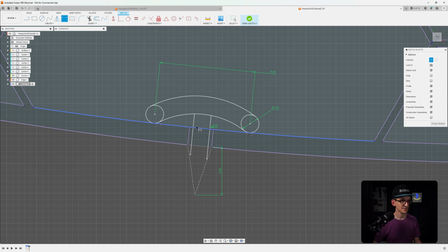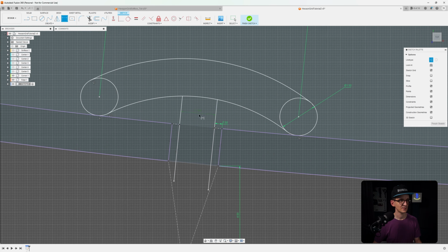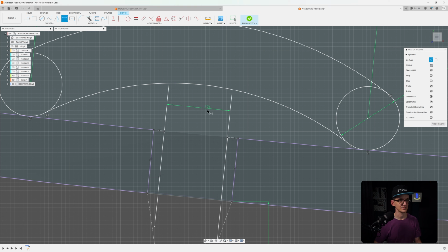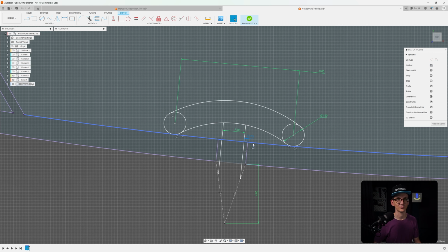And yeah, this is defined, but just as a reference, this is 1.4. Actually, let's get rid of the 0.5 and make this not a generated number, but actually let it drive the geometry. And let's put it to 1.6, and then as an output, let's output how much this is, and it's 0.25, which is still okay for my printer as a clearing. So if you know your printer needs more, you need to make sure that these openings may be wider or the connection here is thinner, right? But for the Prusa Mini, it's actually more than enough spacing to make it work, and the opening is not so imprecise that you cannot fit it in.